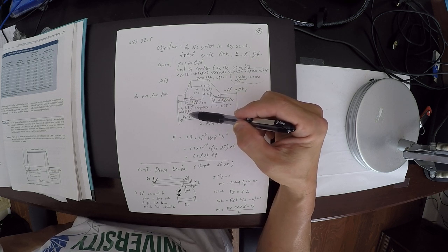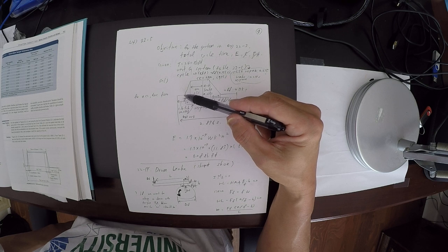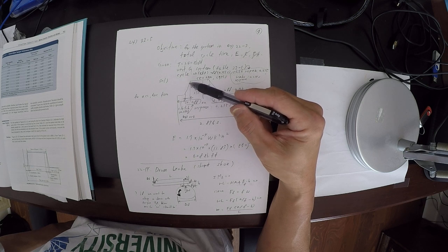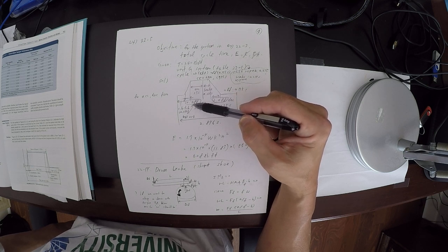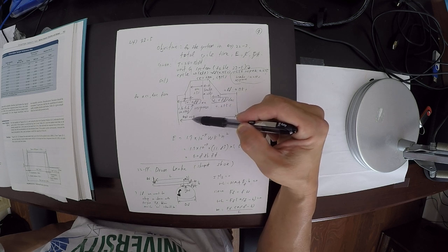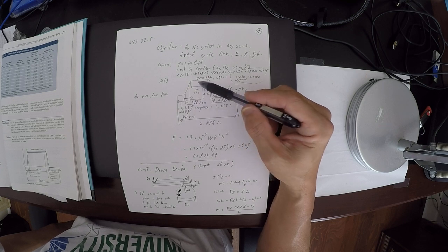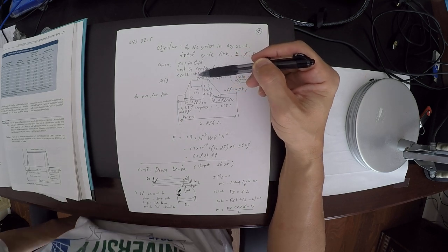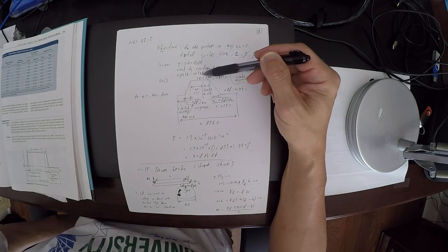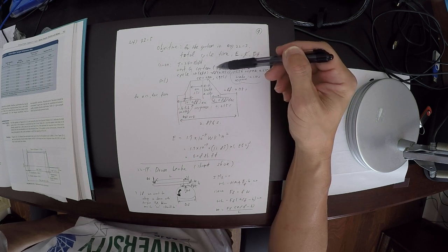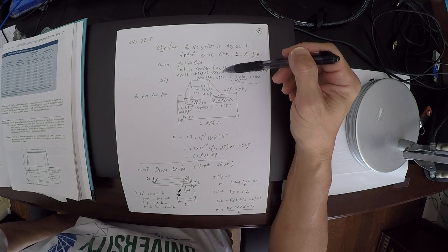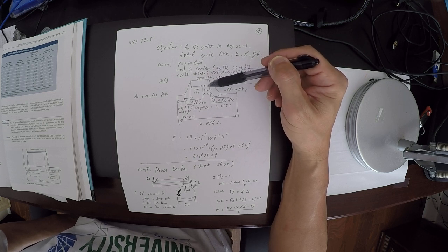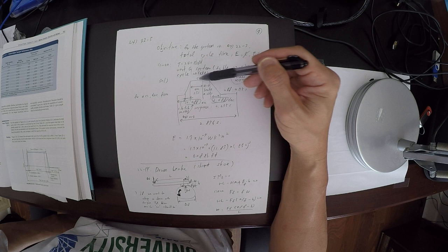So it takes about 0.235 from the table response time, and then once the clutch is engaged, you actually accelerate along this profile for about 0.088, and this number came from the exercise 22-3 to reach up to 550 RPM. So once you get into this, the cycle says you need to let it on for 1.5 second, and then you apply the brake after the on time.